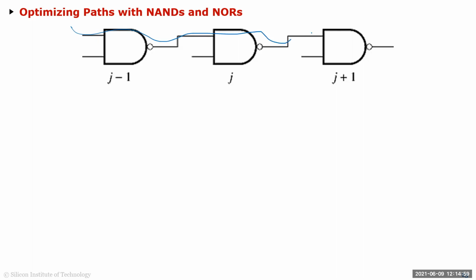So it says that this is the critical path. Critical path means this path here. Any low to high or high to low traverses this path and finally comes out here as a low to high and high to low. This propagation delay is restricting you from operating at full clock speed. Like I said, if your clock period was 100 picoseconds, and this delay path turned out to be 120 picoseconds, then you're going to fail your timing.